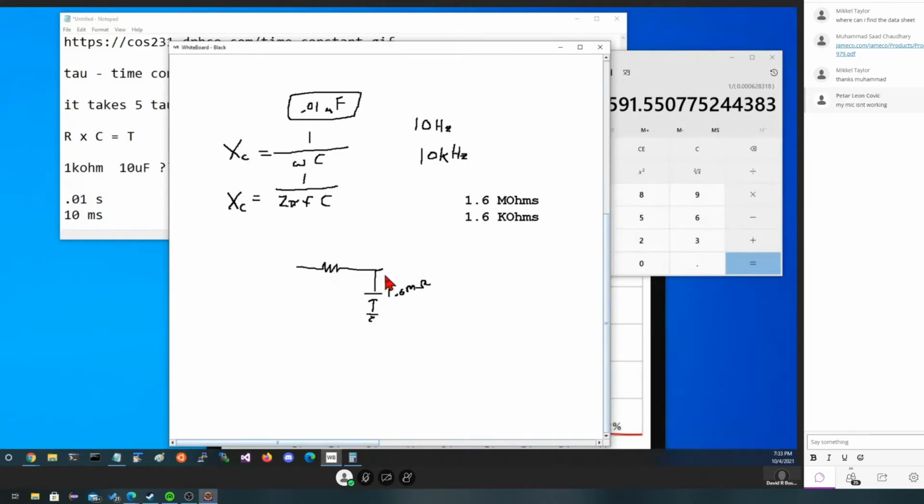Remember we said this is a low pass filter? Well, that showed that this low frequency passes very well. If we change this down here to a frequency of 10K hertz, this number here is going to be divided by 1,000, right? So instead of that, it's now going to be just a 1.6 K ohm resistor, meaning that the significance of this got bigger and bigger. We're going to lose more across this than that, meaning the higher the frequency, the less signal gets through. So this behaved exactly like we would expect it to. And you'll need to play around with these a little bit before they make a lot of sense.